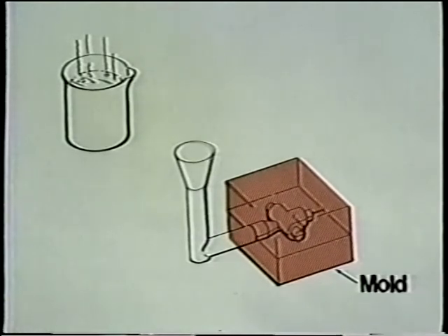The mold is a form which contains the cavity into which molten metal is poured to produce a casting of definite shape and outline. These are produced using various processes. Molds may be either reusable, as in the case of permanent mold and die casting, or broken apart and discarded after each part is produced, as in the case of investment and sand casting.